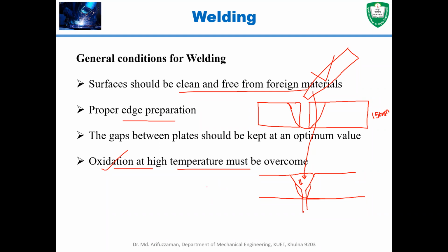For example, if you want to use two cylinders connected together, okay. For example, if you want to connect these two cylinders with the filleted joint, let's say these are two cylinders, pipelines actually. Two pipelines can be joined together with the help of bolts. Okay, you can use the bolts in here, in here, in here. And also if you use the bolt system, then there is extra weight. Okay, but if you use the welding, then it will be joined together. The weight will be less.